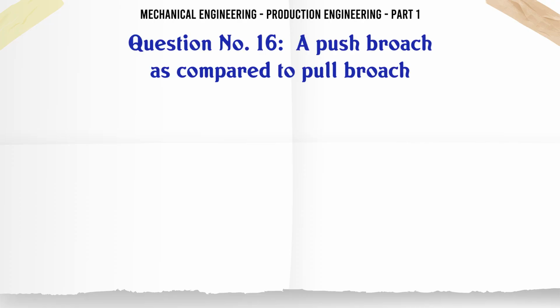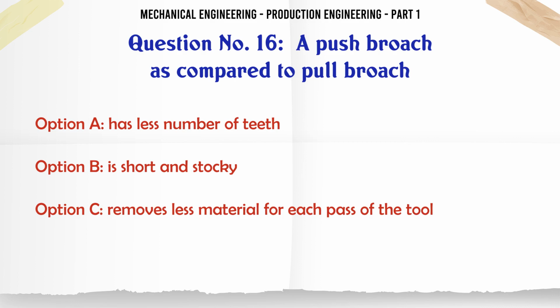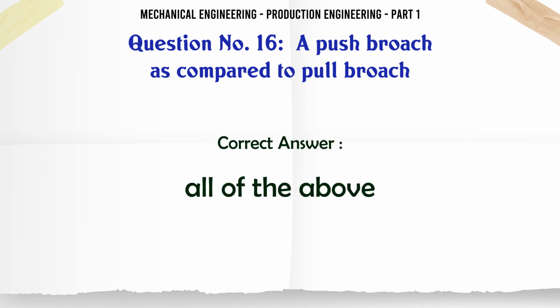A push broach as compared to pull broach: A. has less number of teeth. B. is short and stocky. C. removes less material for each pass of the tool. D. all of the above. The correct answer is all of the above.